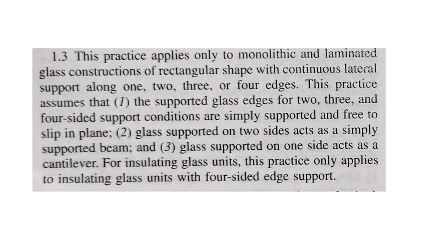Paragraph 1.3 tells us that this practice applies only to monolithic and laminated glass constructions of rectangular shape with continuous lateral support along 1, 2, 3, or 4 edges.